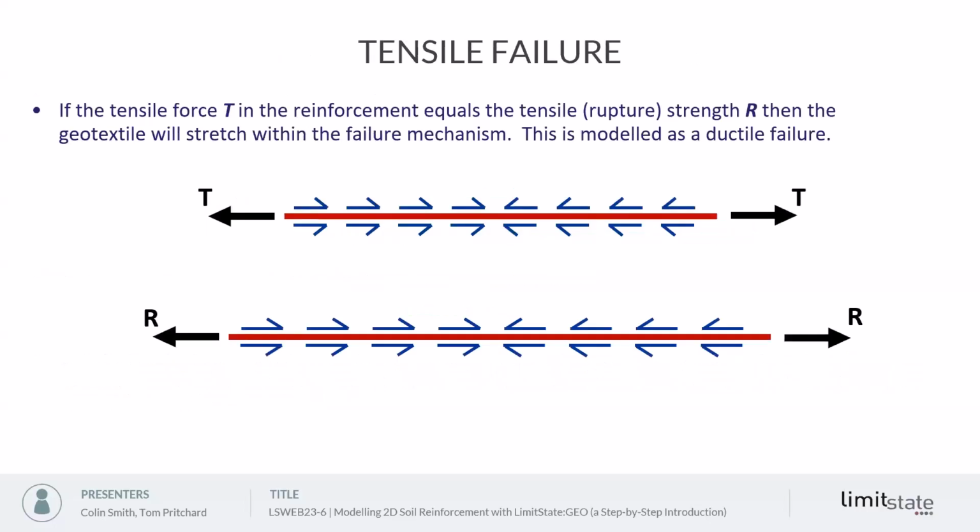It can also model tensile failure within the reinforcement. So if the tensile force in the reinforcement exceeds the tensile strength, then the software will model a ductile failure and the reinforcement will effectively stretch within the failure mechanism.